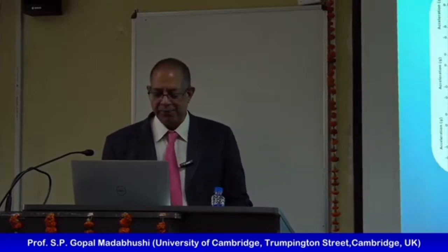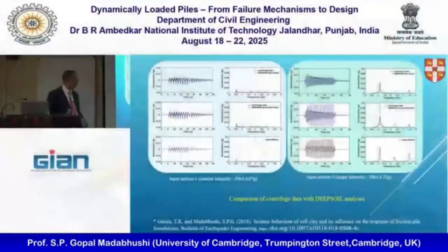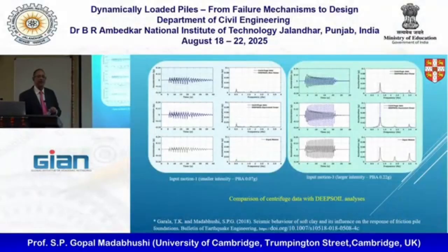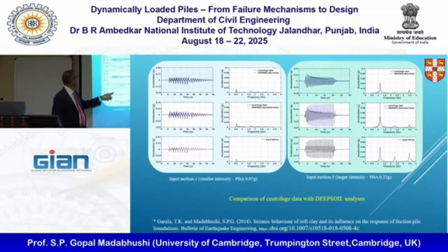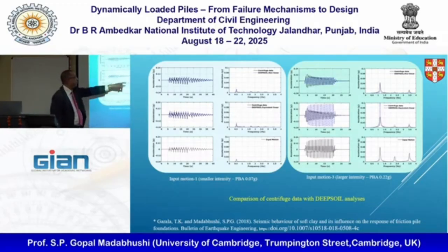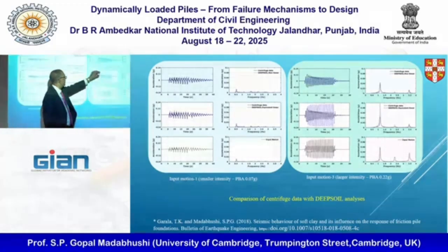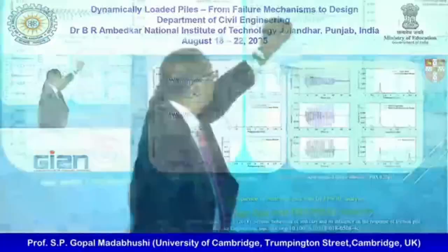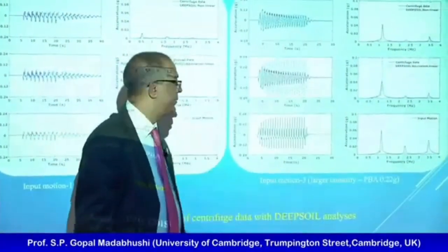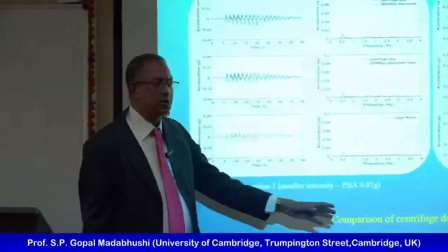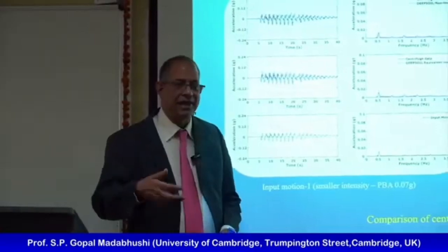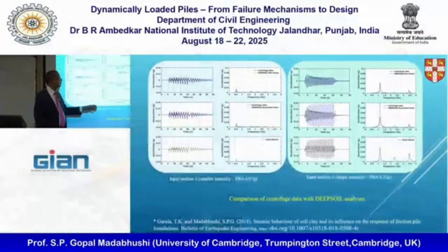So we want to use this to make holes in DEEPSOIL. DEEPSOIL is a computer code which people use routinely to do site characterization. If I put in a small earthquake, everything goes through. With a big earthquake, our experiment is showing the accelerations all fall off, right? But if you do the DEEPSOIL analysis, which doesn't have a failure criterion built into it, it will predict